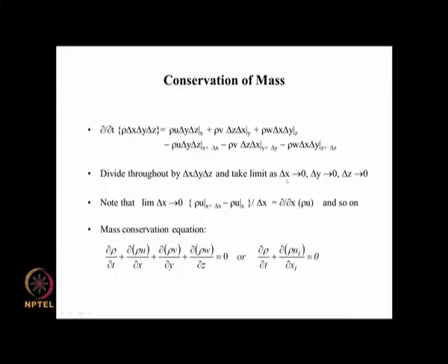So when we say delta x tending to 0, we are looking at something so small that it is practically like a point in our applications, but mathematically it is still large enough that we can think of billions of particles present, so that we can talk about average properties. That is known as the continuum hypothesis. So within that, 0 is defined subject to the continuum hypothesis.